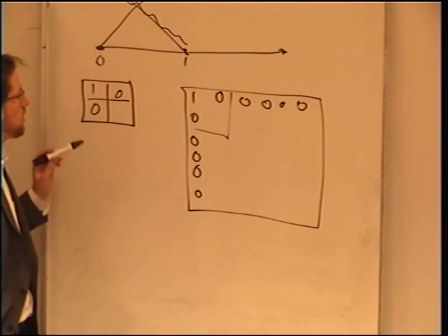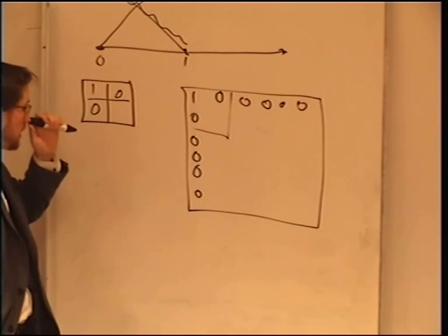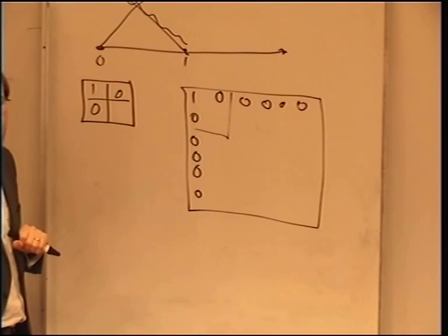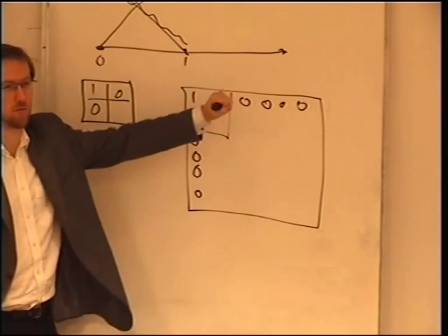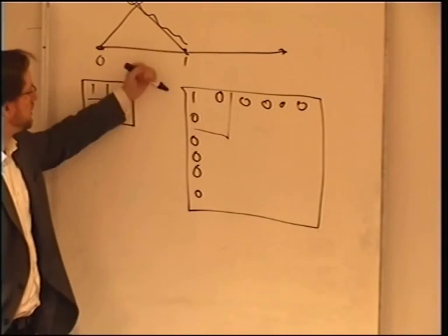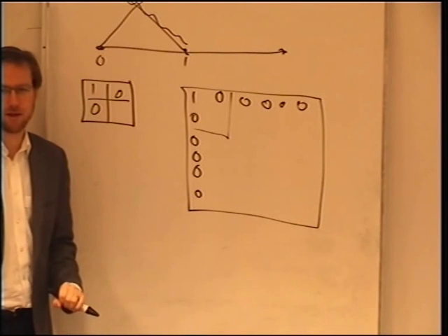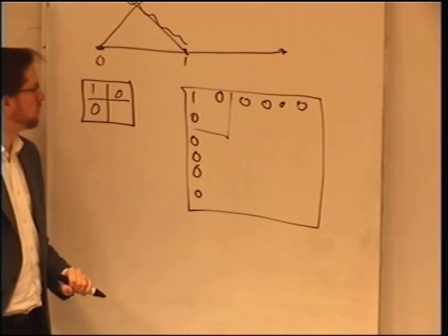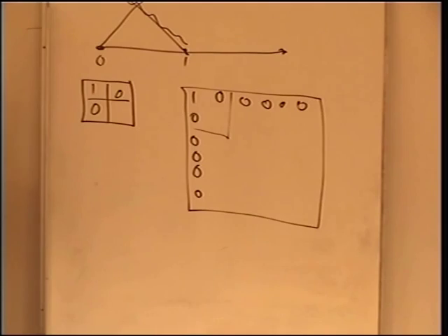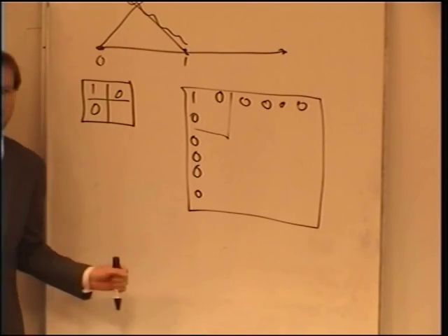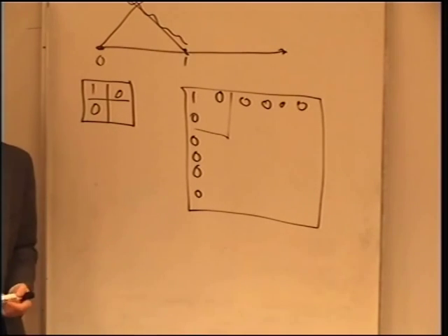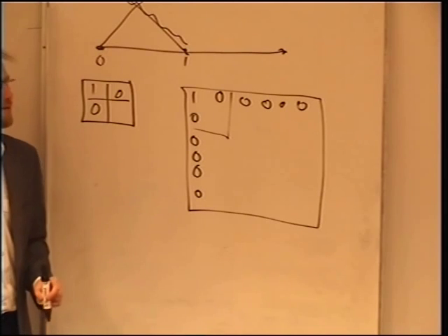The next option is, it turns out you can just zero the row and rely on the solver to put the column in for you. However, the problem with that is if you thought your matrix was symmetric, well, it isn't anymore. So if you thought you were going to use something like conjugate gradient as your solver, you can't anymore. So that's really, really unattractive.